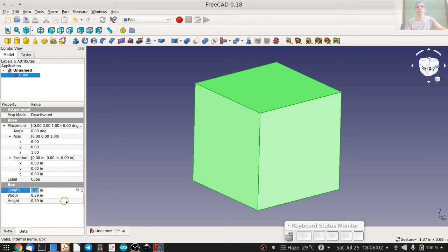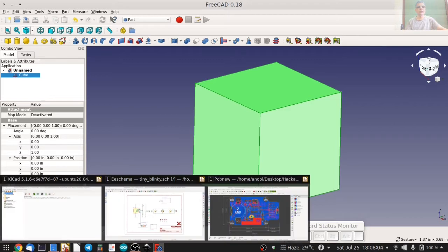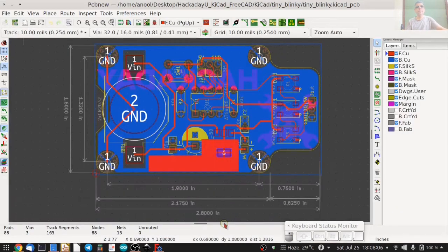If we are trying to do something for the KiCad PCB that we made last time, let's try and make a box. The bottom part of the box that might go below the PCB, and that covers this part of the circuit board, and this much stays exposed. So we'll probably be needing to build a box whose insides are 2.175 inches wide by 1.6 inches tall.